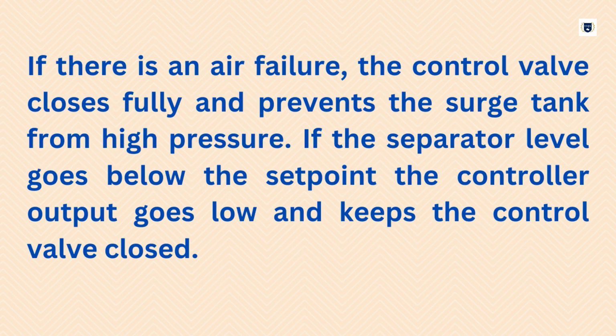If there is an air failure, the control valve closes fully and prevents the surge tank from high pressure. If the separator level goes below the set point, the controller output goes low and keeps the control valve closed.